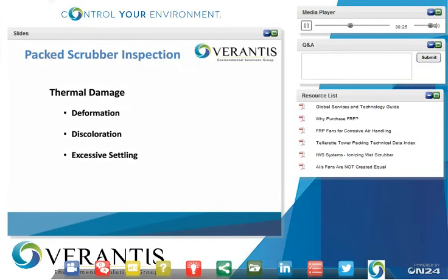Third category is thermal damage. We're dealing with plastic internals here. Obviously, they have limitations as far as heat exposure. First being deformation, and that excessive heat can come from a number of different areas. It can be from the upstream process itself, if there's some type of upset condition that brings hot gases into the scrubber hotter than what it was intended to see.